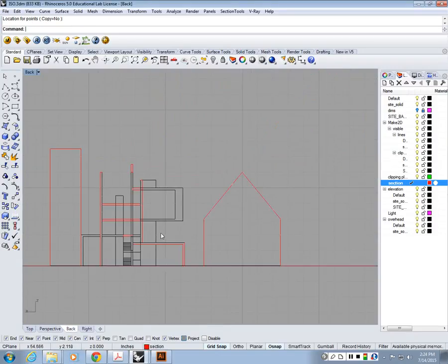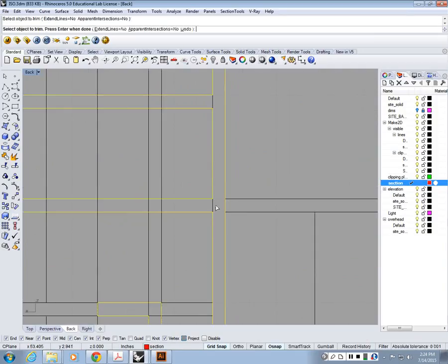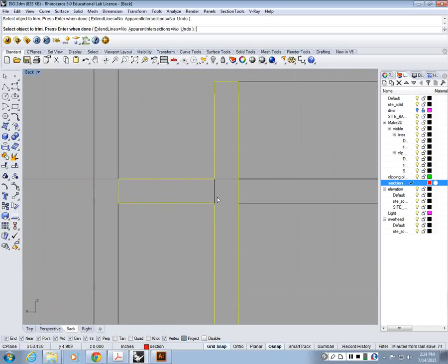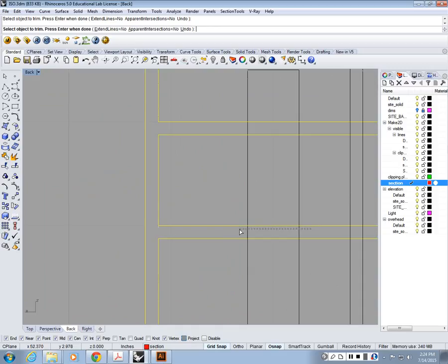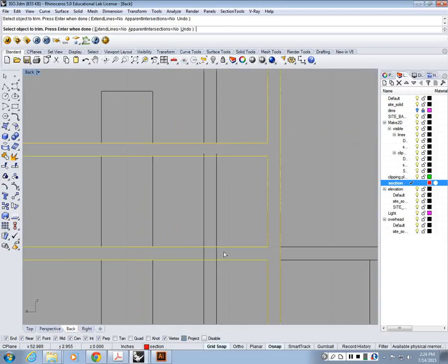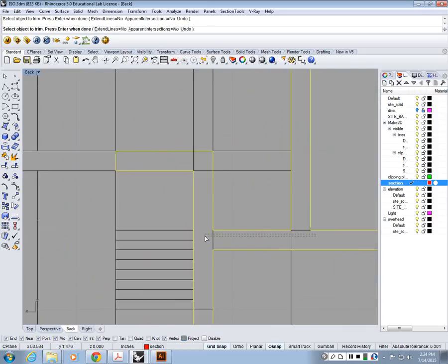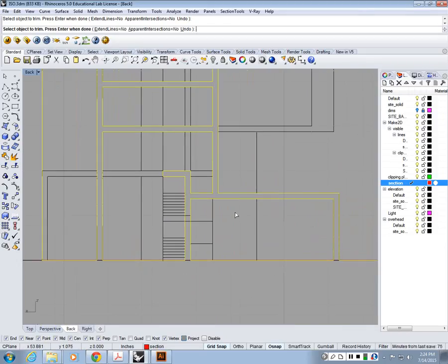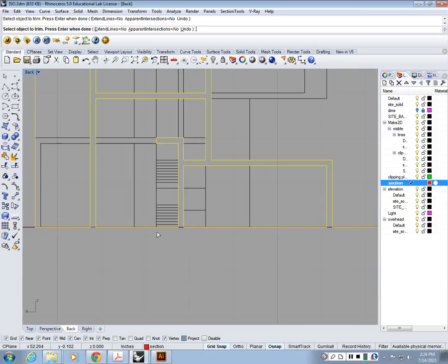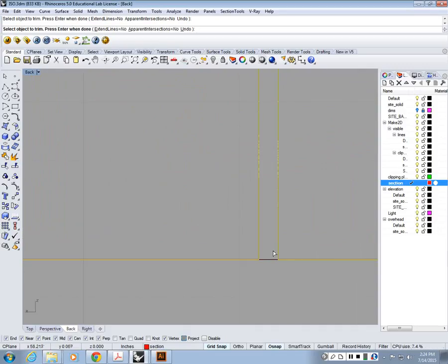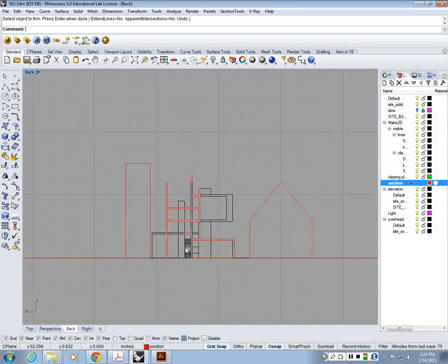So I could come back here, type in trim, select the section, and then clean it up. So I can clean up all these lines. There shouldn't be anything inside the cut lines. Any other lines penetrating through them as well, they should be erased. Here as well. There's a little bit of cleaning up today in mine, so I expect there will be some in yours as well. But that's pretty much it. And these lines, they shouldn't be there as well. So the ground line, we want to leave it as one continuous thick line. We don't want to have any other lines there.